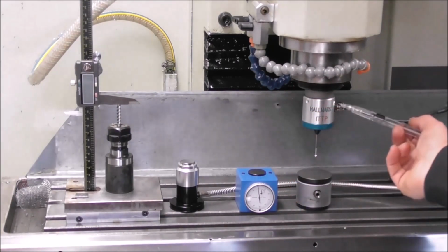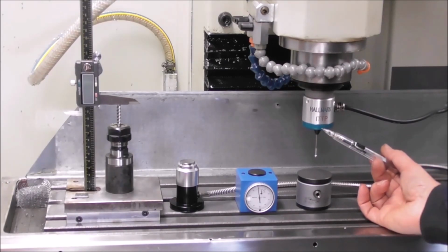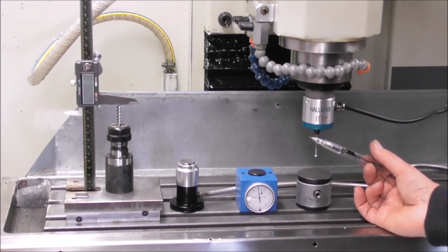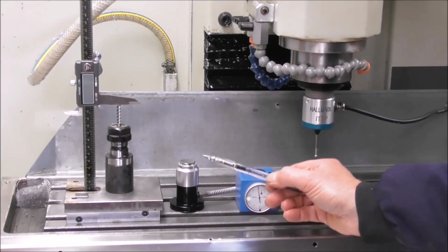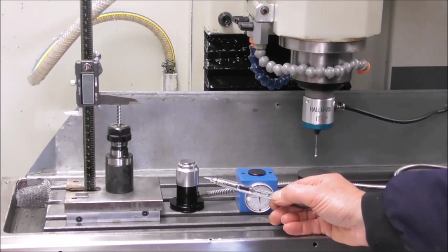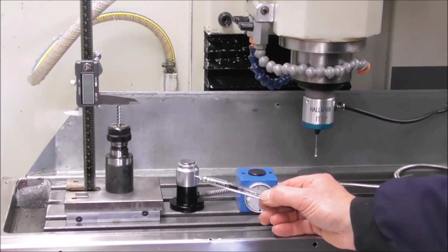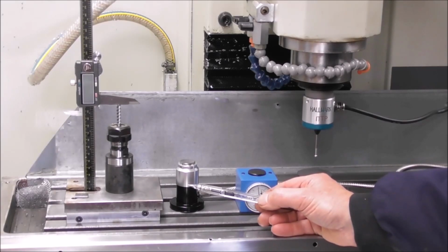Very different thing for a probe when you're setting up your work, there's X, Y and Z in all different shapes, and some very useful probing routines to help you find the position. That will save you a lot of time. An electronic tool setter just used for setting tool length won't really save you much time. You need to be using it in a more advanced situation where you've got an automatic tool changer and different routines for checking tool length, tool wear, and so on.